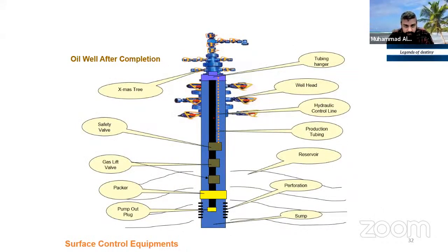After you complete your well, you do your casings and then install the tubing. Then you have the production system, which looks like this one, which has the Christmas tree at the top. Then we have the wellheads, and then we install the safety valve. The purpose of the safety valve, which has a line also here, is this: what if all this Christmas tree fails?